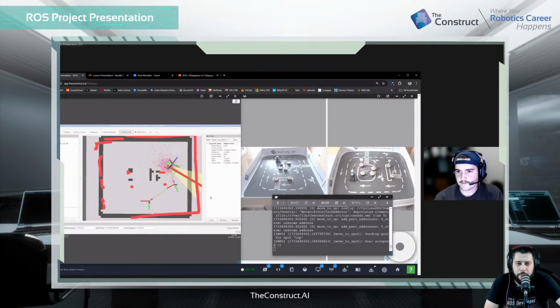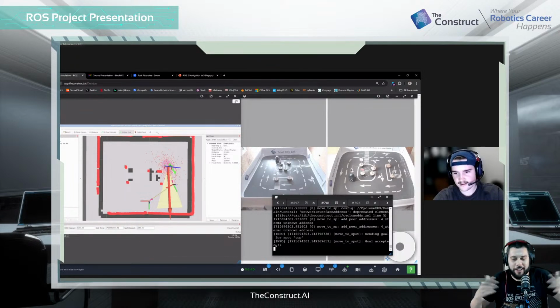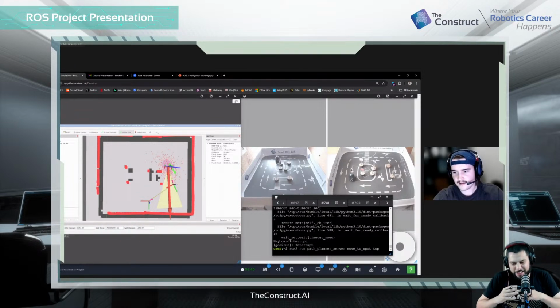Yeah, I think the inflation could be a little bit higher. Well, yeah, and there's a little bit of an added complication here because the robot is actually seeing that stick, not the bottom base of the obstacle. So a lot of times, our students will say, "Oh, maybe my inflation rate is not working." Well, no, it's just because it's not going to see the bottom. Sometimes it grazes against them, but that doesn't mean it's not working. That means it should be a little bit more.